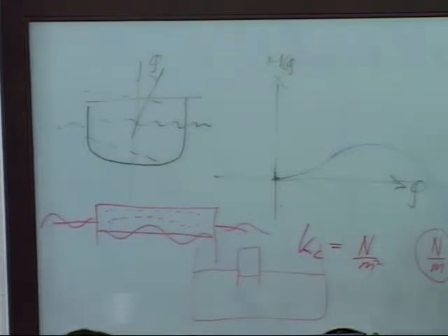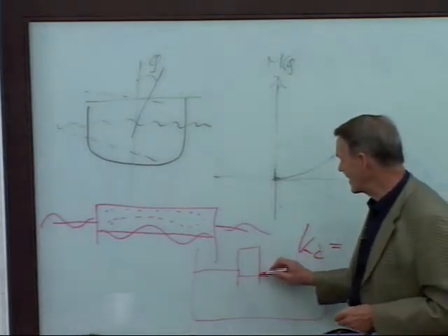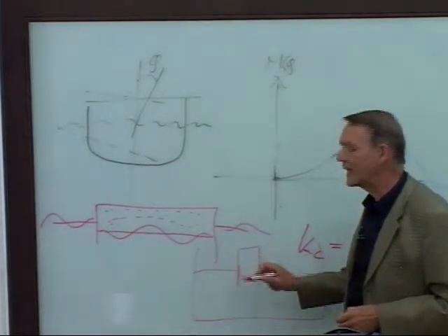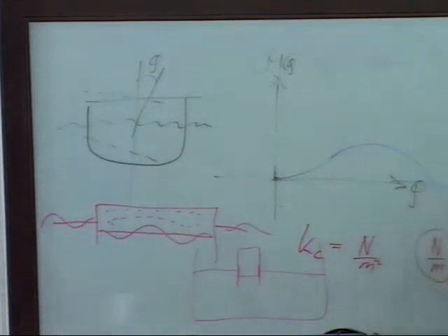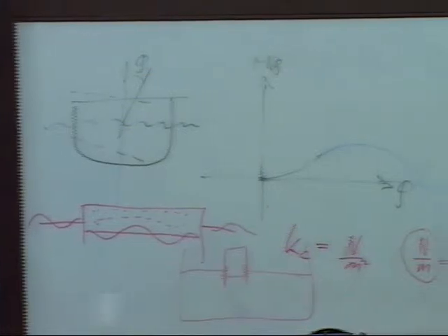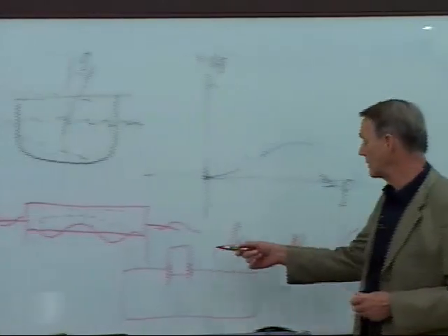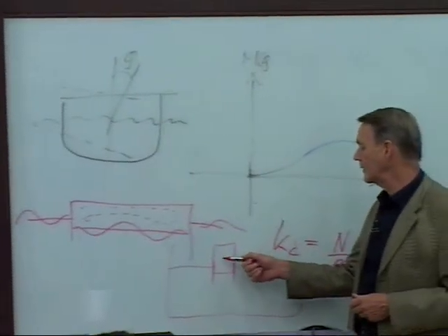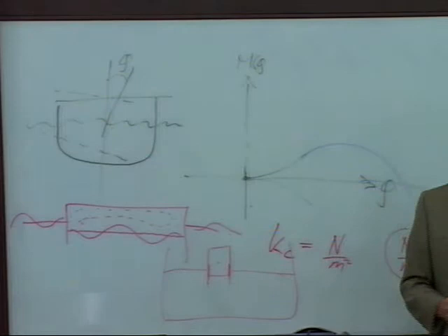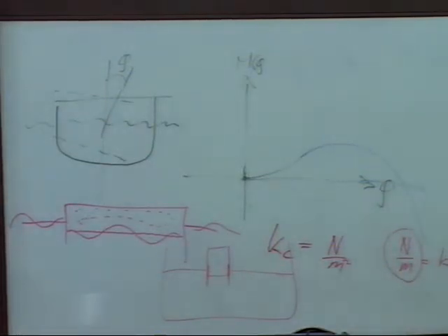Because in fact, the water plane area in this case is just the thickness of the glass. Right? So you have very little restoring uprighting moment in a situation like this. And of course, also if this is a glass or a cup of some sort, the center of gravity will be up there. So there's no stability of a system like that. So that's the bad news.